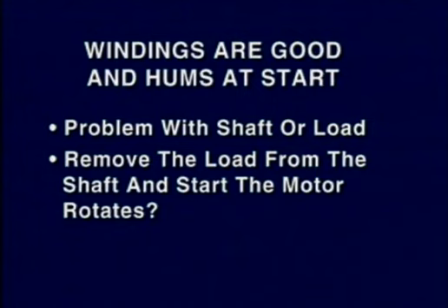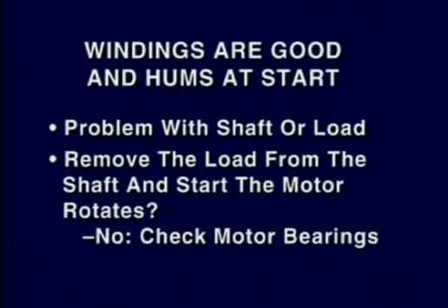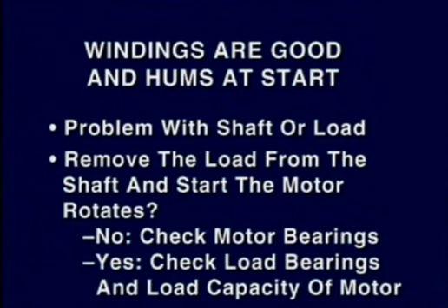Remove the load from the shaft and start the motor. If the shaft does not rotate, then you need to check the bearings. If the shaft rotates when started, you need to check the load's bearings and make sure that the load capacity is not being exceeded for the motor.